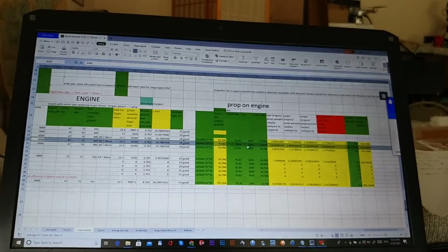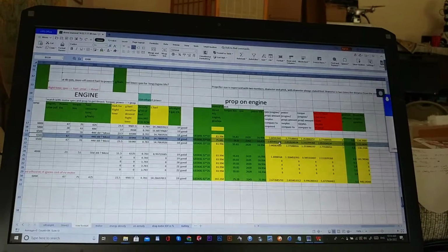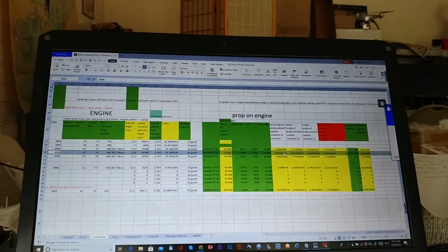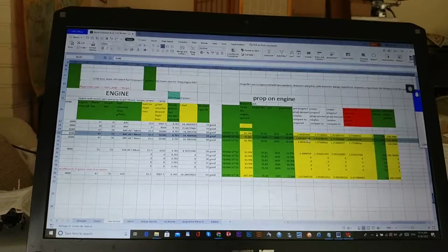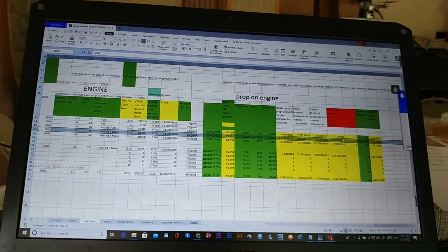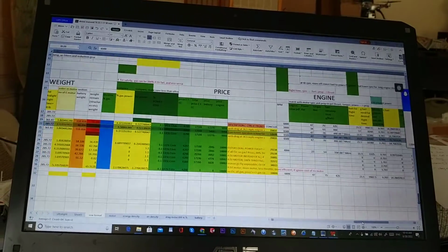And with that torque, I input to the prop. I match it with the prop data sheet, what torque, the power required, and what thrust it produces. And this thrust is added to the total one. Let's go back to C.